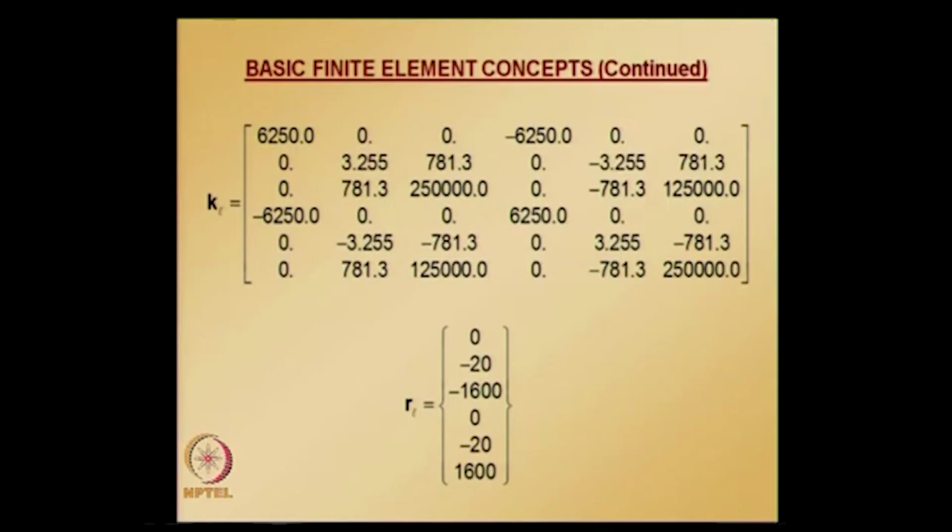Because of the boundary conditions, all the degrees of freedom at nodes 1 and 3 are 0. There is no need to assemble the corresponding rows and columns. Further, since the specified values are 0, the corresponding columns will not contribute anything either. So, in the following global equations, only the terms associated with node 2 are written.